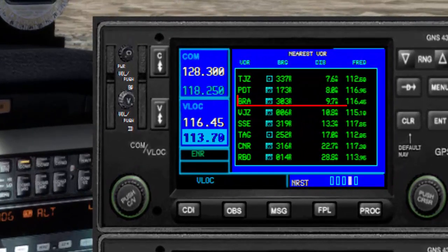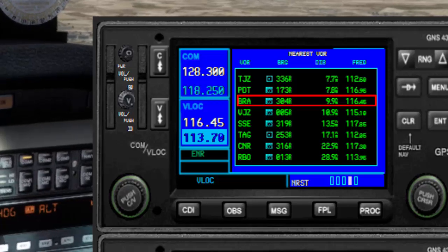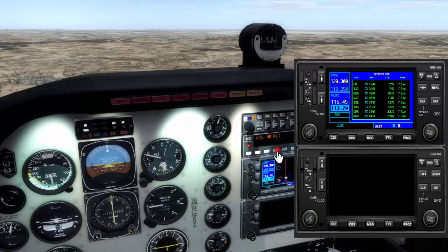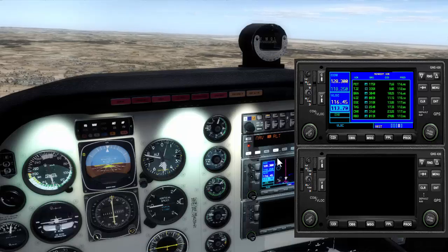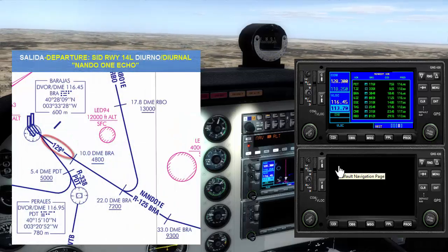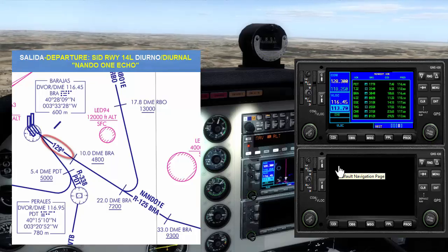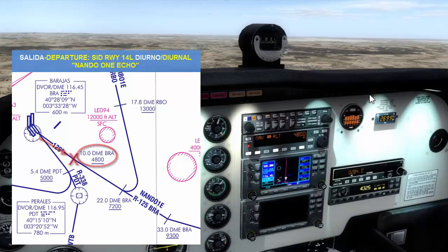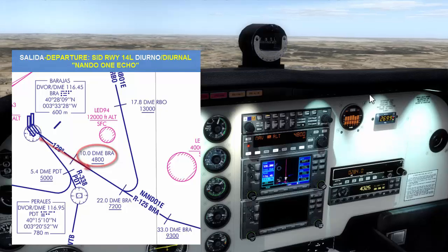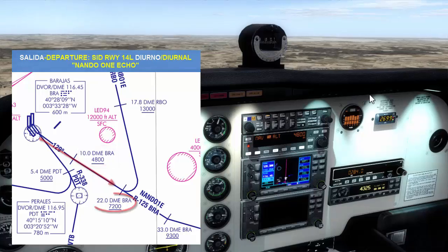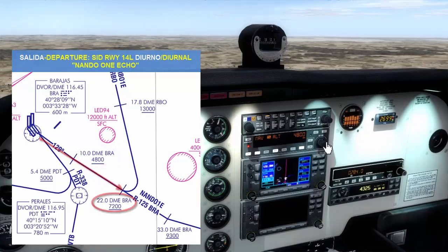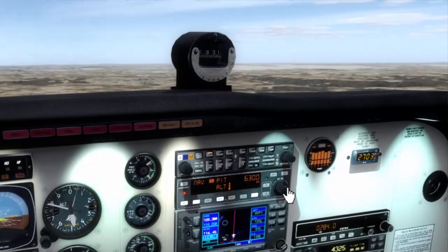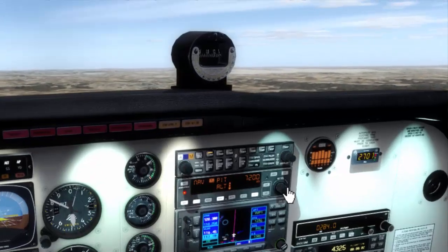So we're taking a look very close to the Barajas VOR. And as you can see, we are right now at 10 nautical miles. Okay, so we proceed right now to follow the Barajas VOR radial. Exactly, we did that segment that you see in the circle. We traveled on radial 129, and then we reached 10 nautical miles from the Barajas VOR. At that particular point, we were at 4,800 feet, and then what we are doing right now is following the next altitude that you see there.